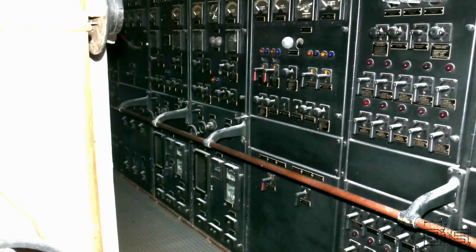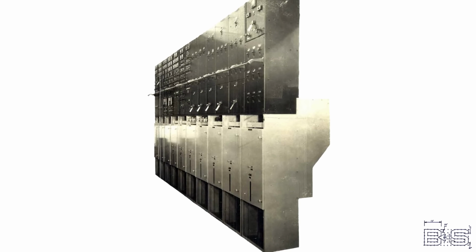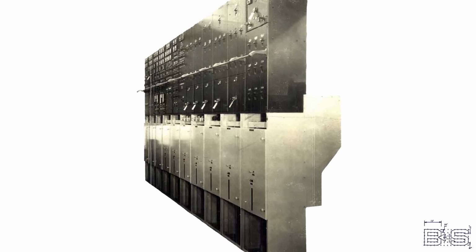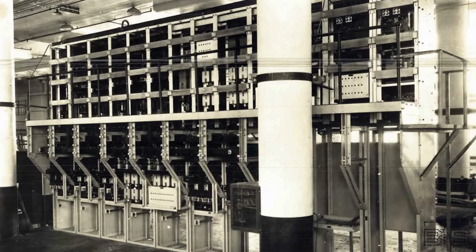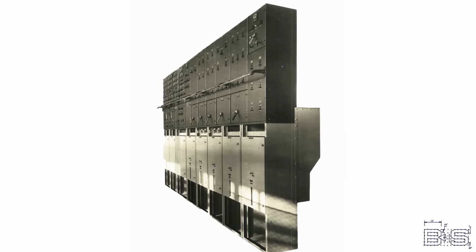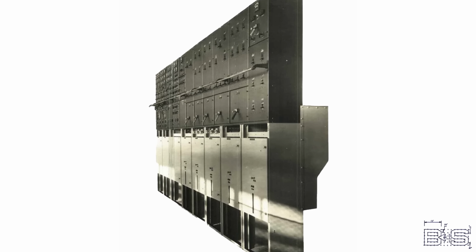These turbo generators are wired directly into a switchboard. In the case of the number 1 machinery room, this is designated the forward turbo generator and distribution switchboard, while the number 3 machinery room has the after board. These are massive 2-story structures that contain metering, synchronizing equipment, controls, and circuit breakers for the 450 volt AC power and 120 volt DC power systems.